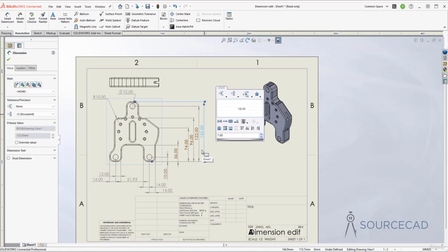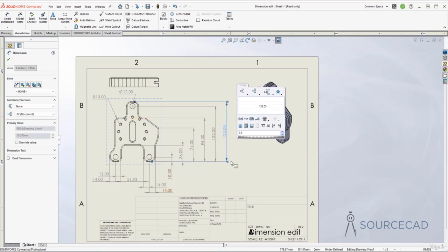So in order to just make it work for every single dimension, you can click here and that's going to reset all the dimensions. So click, which is auto arrange the spacing. So it will automatically space every single dimension in this set evenly. So if I click here, now it will space it evenly. So there we are. Now, after evenly spacing this, if you feel like the spacing is less or maybe more, then you can change it here. For example, maybe let's just make it 1.5 and press the tab key. Now the spacing is more between all of these dimensions.